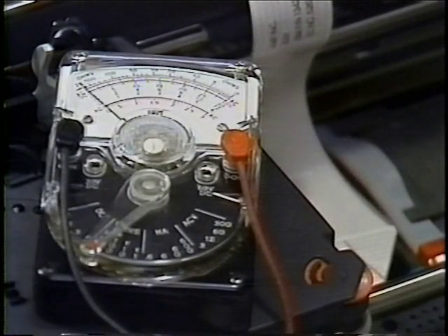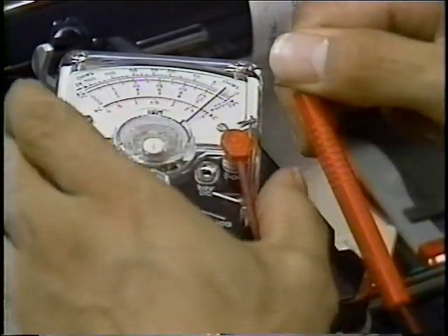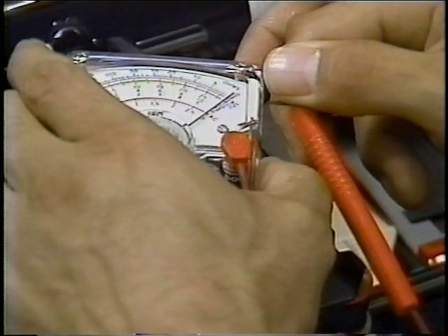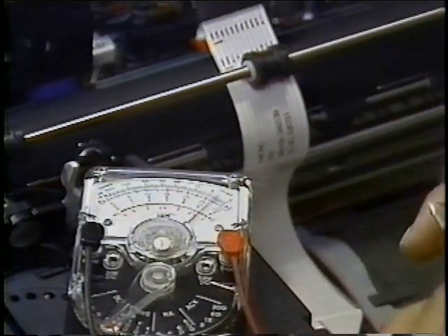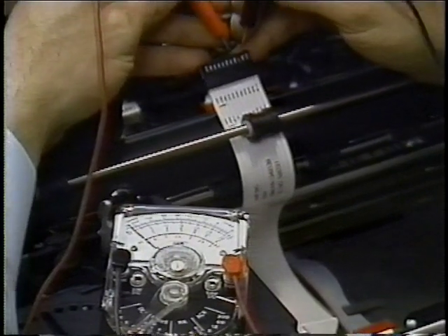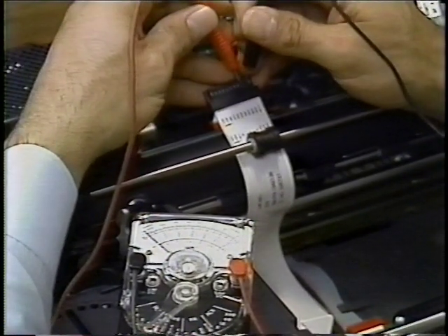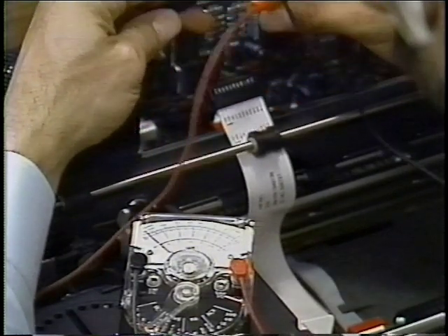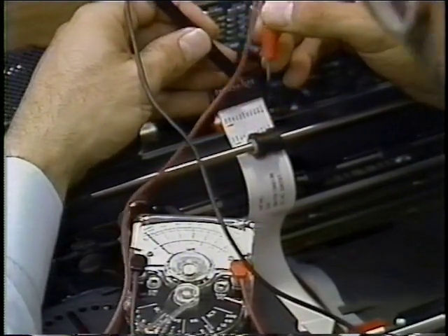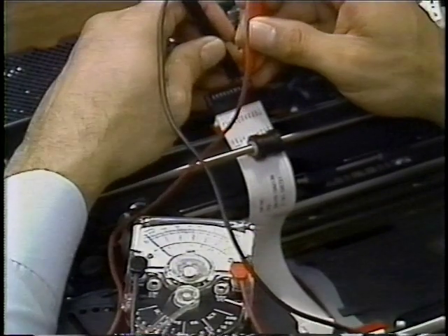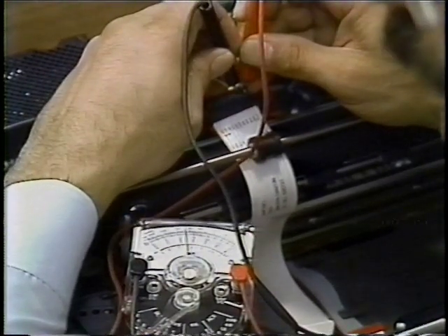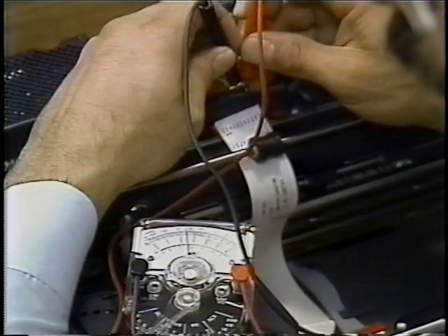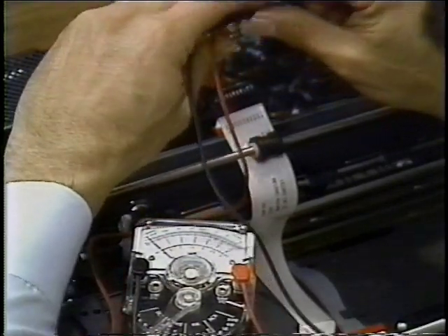To check the homing LED, measure the resistance of the LED in both directions. Unplug the carrier cable. Using the ×1 k-ohm scale, put the common lead on pin 10 and the VOM lead on 9. The meter should show no continuity. Next, reverse the meter leads on the connector pins. Now the meter should read mid-range on the ohm scale.